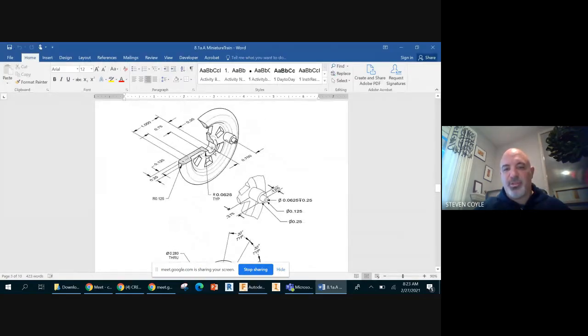So one of the things we look at here is our dimension from here. From the center of the first sketch to here is going to be 0.7. Then here we're going to come out. We have to draw, basically again, 3 circles and extrude them. You can use your hole tool here if you wanted to make a point to make that final hole. That's where the linkage peg is going to go in.